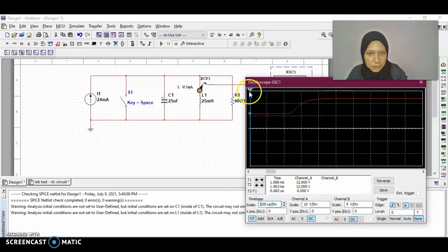The value of current also is equal to 12 milliamps. And when the switch is open, it will gradually increase to its steady state or the final current, which is 24 milliamps, after a long time. And the same as when the resistance is equal to 500, when it is increasing, it never overshoots the value of current steady state.